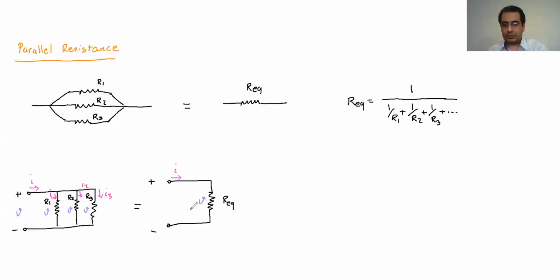So that's a very important point. With the equivalent resistor, we cannot bring the I back to I1, I2, or I3, but we can bring V back, because whatever V is here is the same as V here. So you can put the V back here from the simplified circuit and then start analyzing the more complicated circuit when we want to do that.